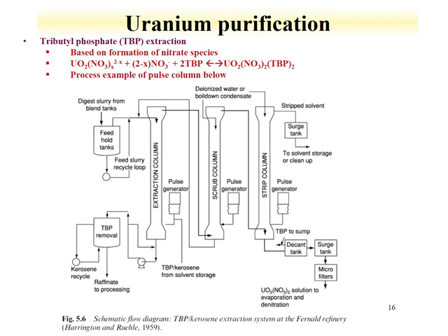The aqueous phase would be added to the pulse column, and drops migrate down. As that drop moves down the column, it will form the uranyl nitrate tributyl phosphate species, which then gets extracted into the column.